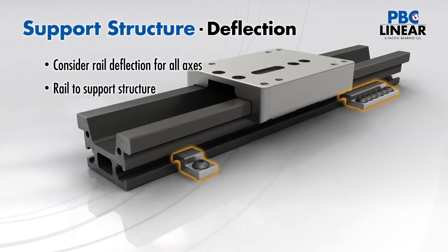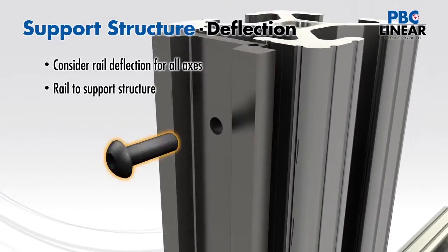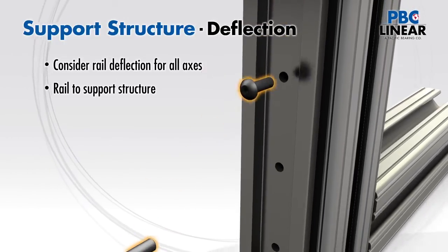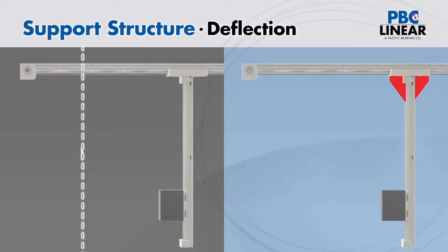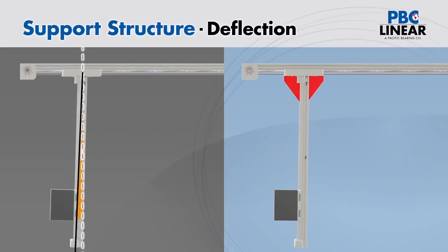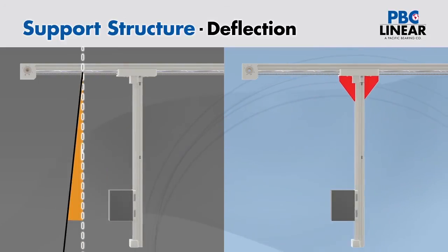For example, T-nuts may be adequate to connect elements in a short stroke or in dual support situations, but for longer stroke or in vertical Y-axis locations, additional support gussets may be required to eliminate deflection or a swinging pendulum motion.